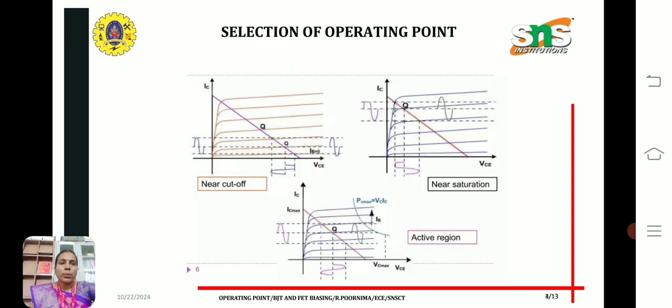Now, selection of the operating point: when we select the operating point near the cutoff region, the signal will be distorted. For example, consider the collector current. Here the negative half of the signal is clipped off. Also, near saturation, consider the waveform of the collector current. Here the positive half is clipped off. In the active region, the Q point is chosen so that we get the signal without any distortion.